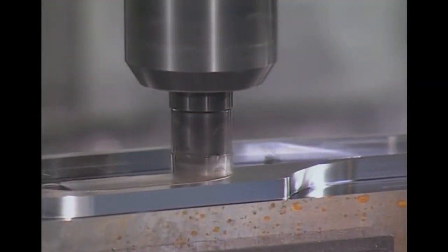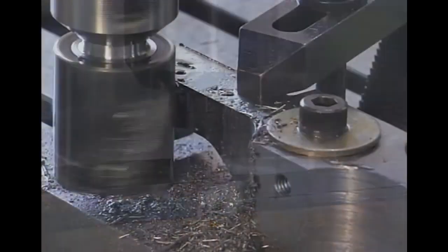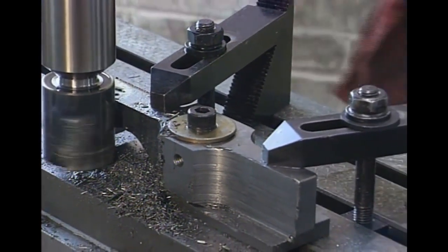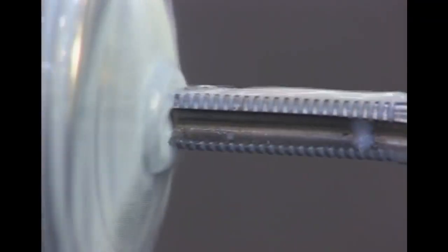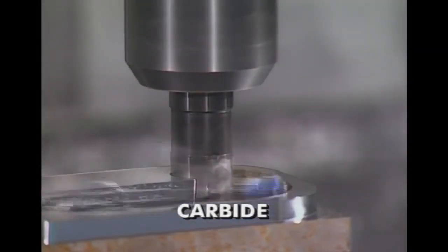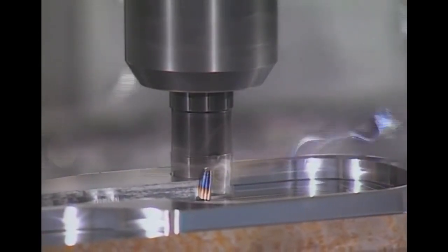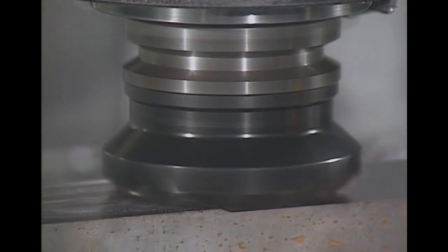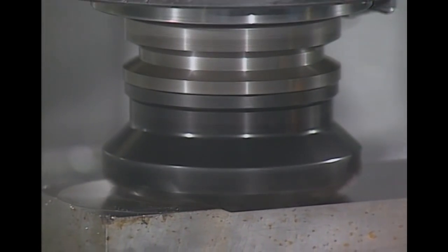In industry today, high-speed steel tools have been replaced by carbide tooling in many areas, but high-speed steel tools are still preferred for some tool room and low cutting speed operations, and for certain tool types such as small diameter drills, taps, and end mills. Carbide tools were introduced from Germany in the 1930s and today are the most widely used cutting tool materials. Carbide and coated carbide tools in general cut about 3 to 5 times faster than high-speed steel and operate at temperatures up to about 1200 degrees centigrade.